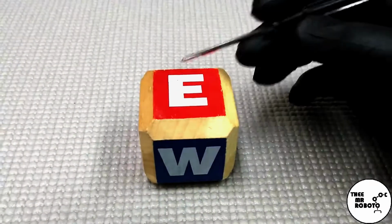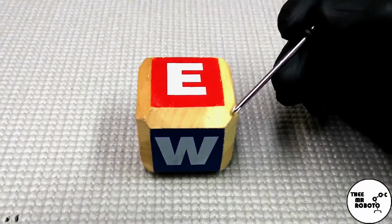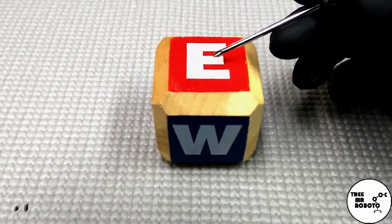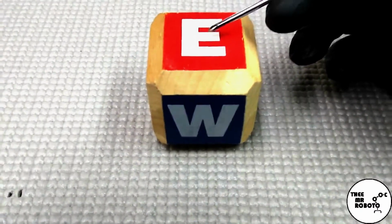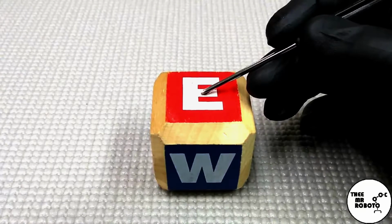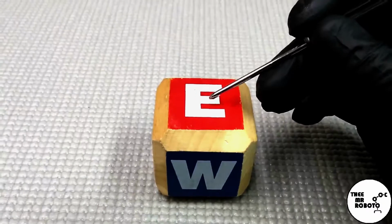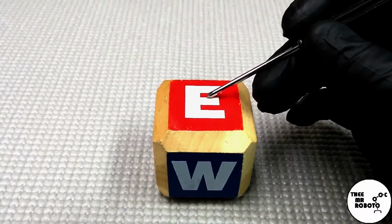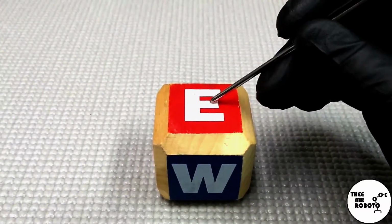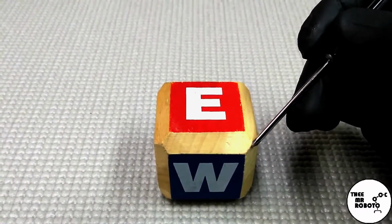You could define it in the middle, with the origin in the middle, but that can be kind of hard to create, because you have to use the tool center point to actually move it to the origin and create your X, Y, and Z. So typically when you're creating this type of coordinate system, you would have a point on your end-of-arm tooling or something like that, and usually you would set it to a corner.